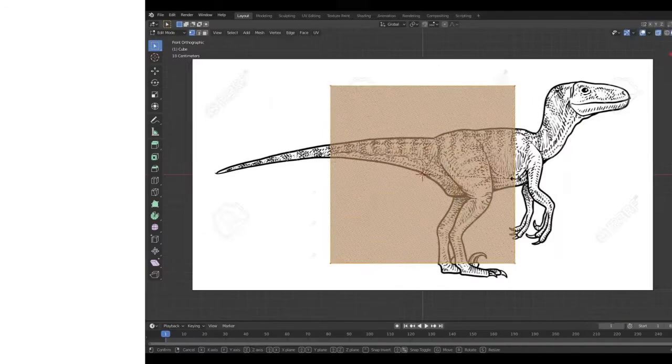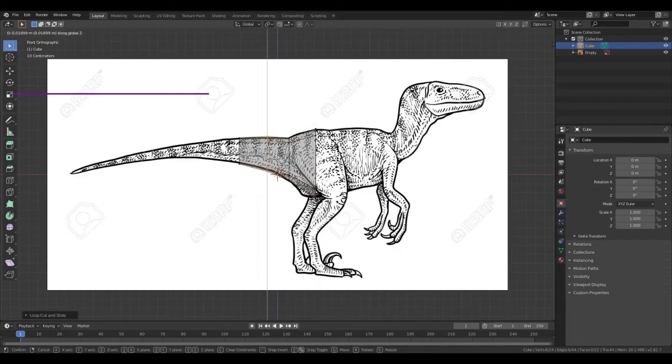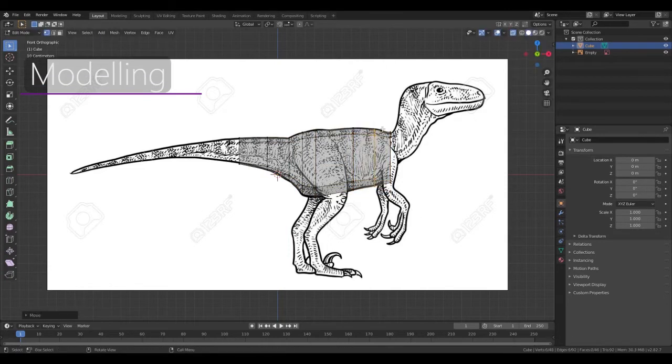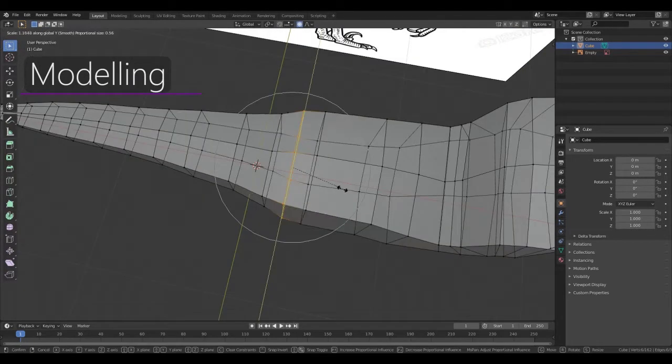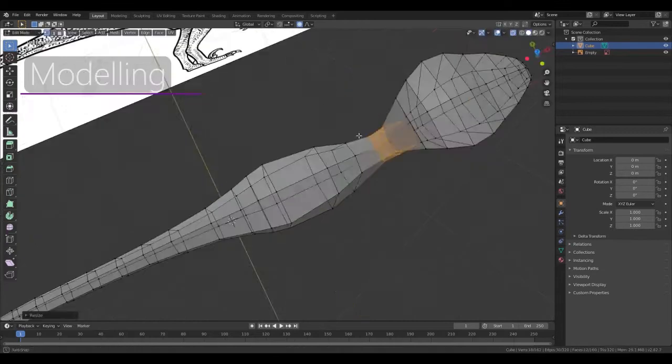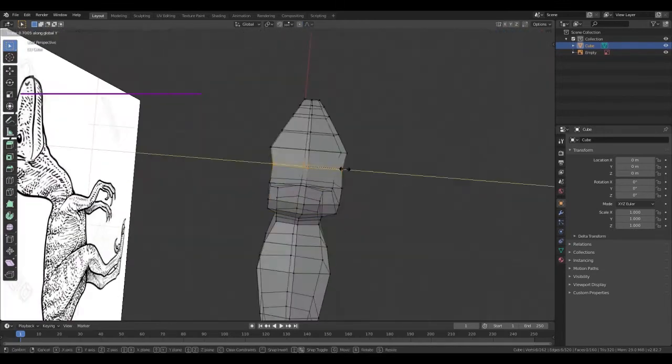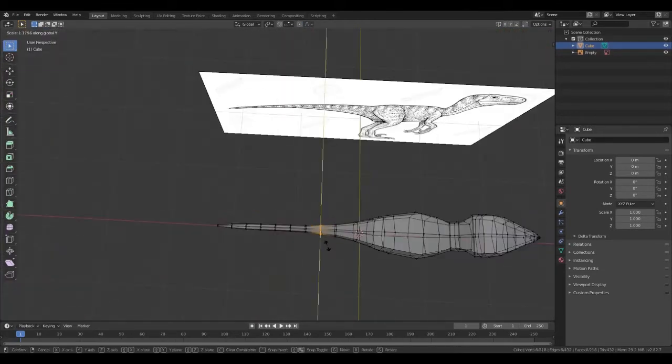One of the main challenges in terms of assets was the creation of the dinosaur, in particular, the modelling and sculpting methods. Creating the creature was a fairly long process, though thanks to the various facilities available within Blender, everything was easy to organise. The model was formed from a cube mesh, which was taken into edit mode and modified with edge loops and extrusions. Scaling each group of vertices had to be done carefully in order to keep the mesh as naturally symmetrical as possible. Proportional editing proved useful in forming the basic overall shape of the mesh.